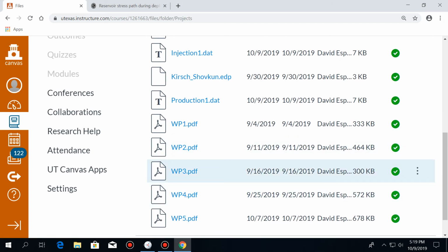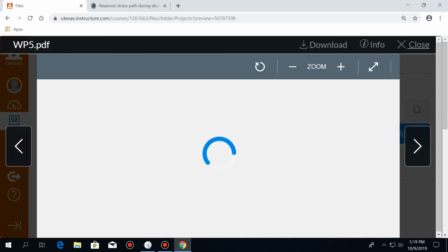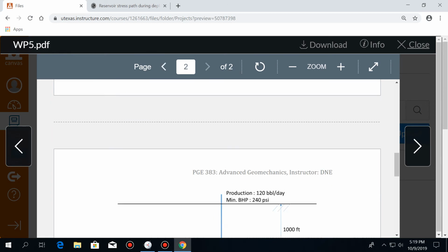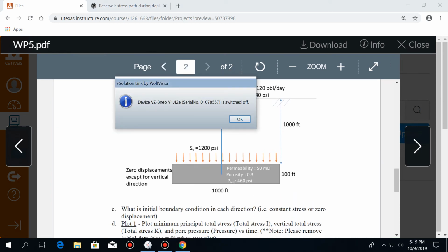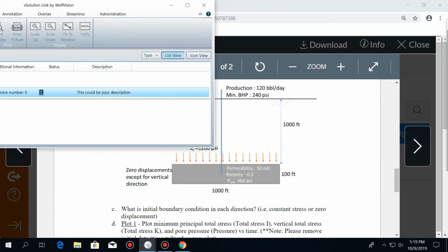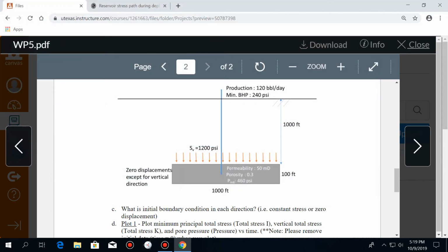Yes, go ahead, Jack. So you have this equation, and are you using this only as an indication, like relevance, or do you actually use this equation to calculate the height of subsidence? This equation is to calculate the deformation of a reservoir at the top of the reservoir unit. Whether that goes on surface or not, that depends on other things.